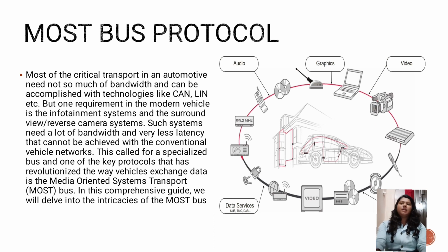Now, the MOST bus protocol. MOST stands for Media Oriented Systems Transport. In automotive, needs that do not require so much bandwidth can be accomplished by technologies like CAN, LIN, etc. But one requirement in the modern vehicle is infotainment systems and surround view reverse camera systems. Such a system needs a lot of bandwidth and very low latency that can't be achieved with the conventional vehicle networks.